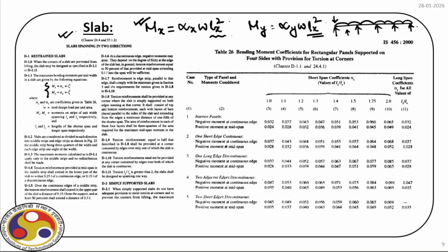And depending upon whether it is the outer support or inner support, the value of hogging moment will vary, and we have to find them first before we start designing. But here in the code, we have this dedicated clause, and with these two formulae, we can actually find out Mx and My directly without solving this structure, right?